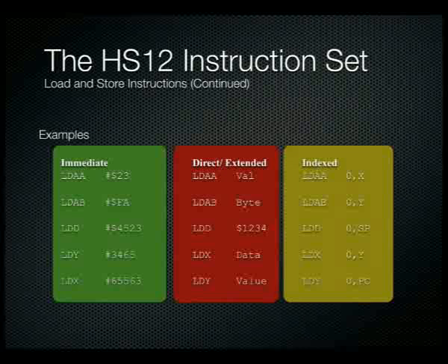the most significant byte. So it simply loads 2 bytes out of memory. It's stored in big endian notation. So we have the MSB at the memory location we're referring to, and we have the LSB at the memory location directly after it. So you've got to keep that in mind when you're dealing with 8-bit or 16-bit registers, that if you load to a 16-bit register, you'll effectively end up loading 2 bytes out of memory.